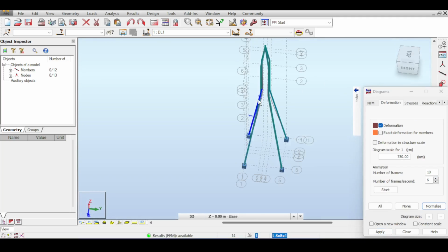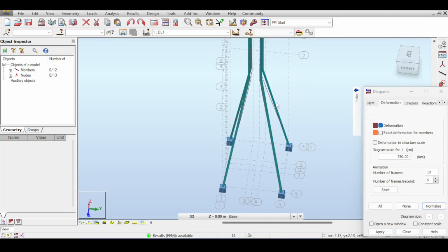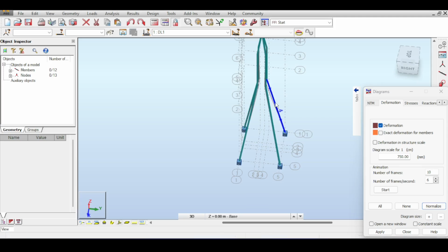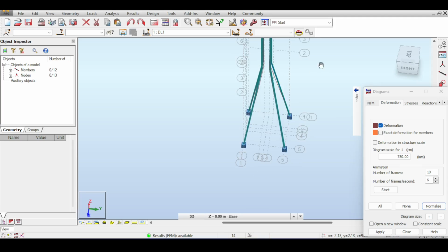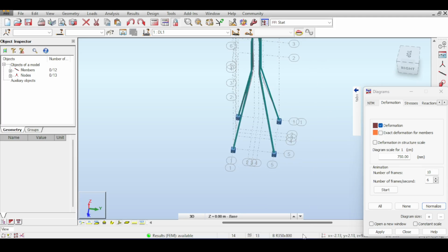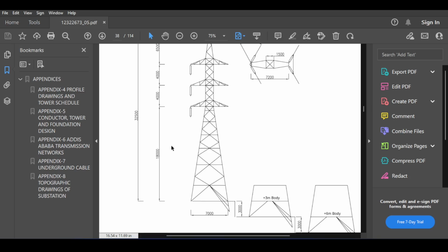Of course, the deflection horizontally is large because there is nothing stiffening the structure in the horizontal direction. Okay, so how can we fix that? Well, of course, we need to start putting in our diagonals and our verticals. Now, truth be told, I personally dislike the drawing suggested here by JICA because you can see that it causes all kinds of practical problems. I mean, take a look.